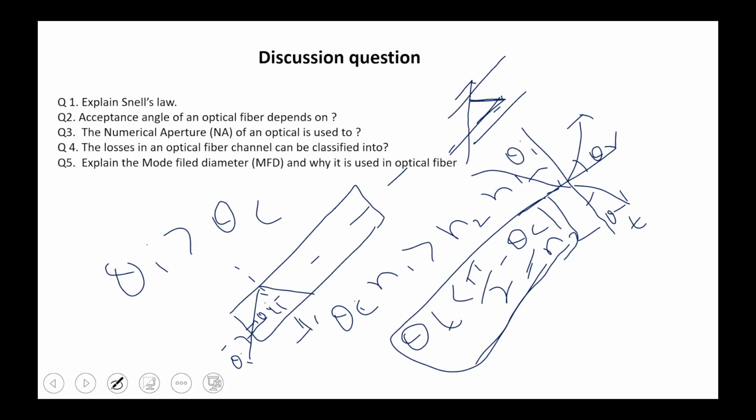During fabrication, extrinsic losses occur due to OH ions dissolved in the water content. If we do the fabrication using purification techniques, then the extrinsic losses occurring due to the OH ions can be reduced. So can we minimize the intrinsic losses due to the SiO2 glass? We cannot minimize intrinsic losses, but we can minimize extrinsic losses. Okay, good, good, Namita.